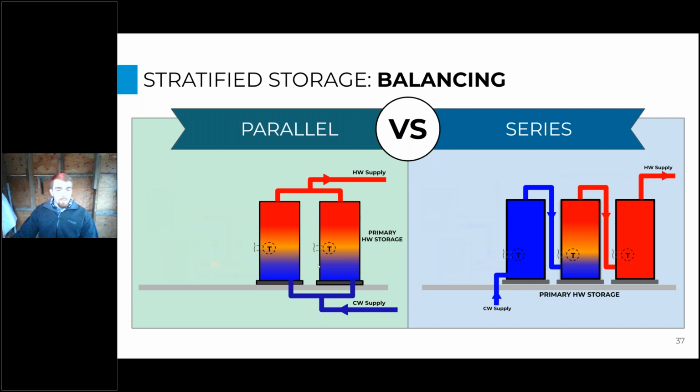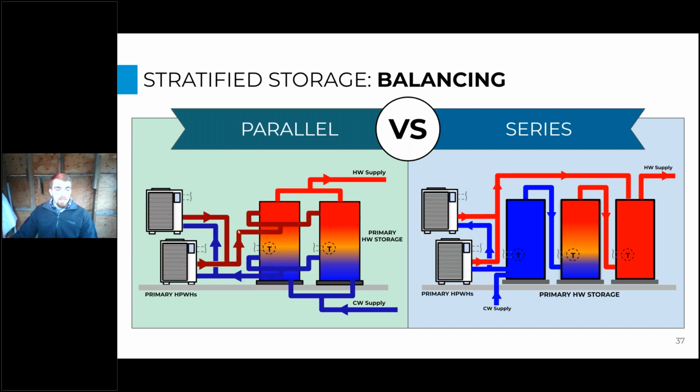So it's also important to balance your heat pumps as well, because you want to recharge your tanks at an equal rate, and that's equally as important as discharging your tanks at an equal rate. So that's not really an issue with in-series tanks, because you just have that one single flow. So any pressure drops throughout this system will result in a change in flow throughout the entire system, rather than a change of flow through an independent tank. And same with the heat pump balancing itself. All the heat pump flow is just going back into this final tank and back charging through the entire series. So you can't disproportionately charge tanks in a series configuration.